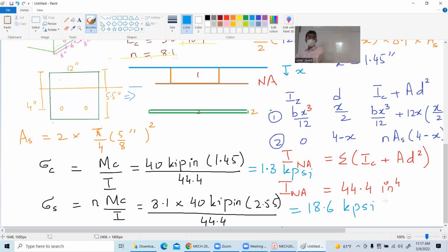Before I take your question, just one comment. So what exactly is rebar? What is the point of concrete then? When load is being applied, below the neutral axis you have concrete, and we have talked about the fact that concrete is not good in tension. So what's the deal with the concrete that is below the neutral axis line? The whole purpose of that concrete is that it is holding the rebars, those metal rods, in place. And those rebars, two of them, are taking the load. Are you getting my point? Yes.